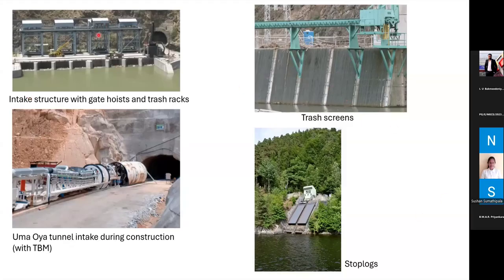And we have the gate hoist. Basically, when you want to block the intake, you can use the gates in the intake to stop the water going into the tunnel intake, and we can do maintenance on the tunnel.